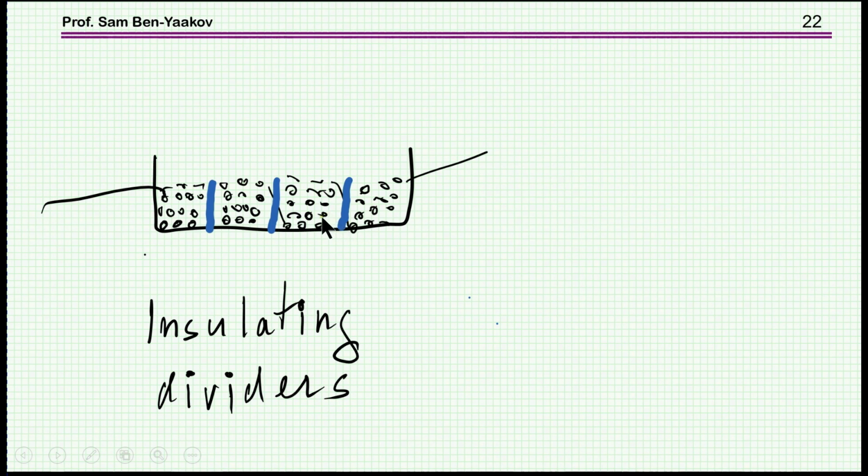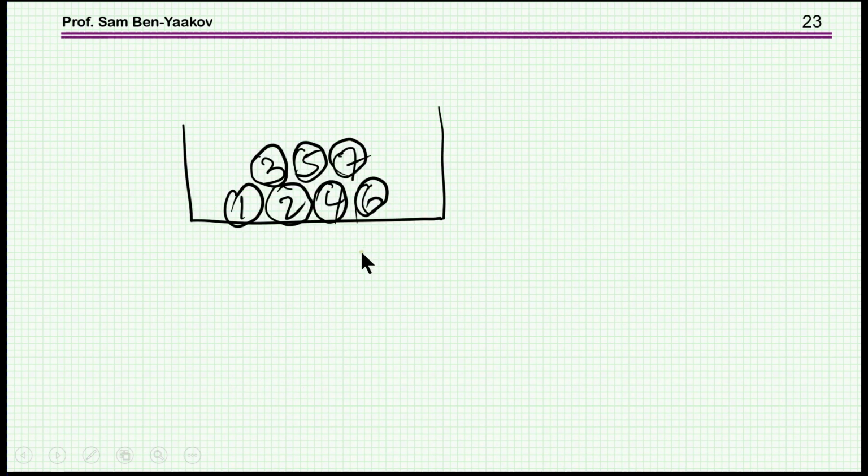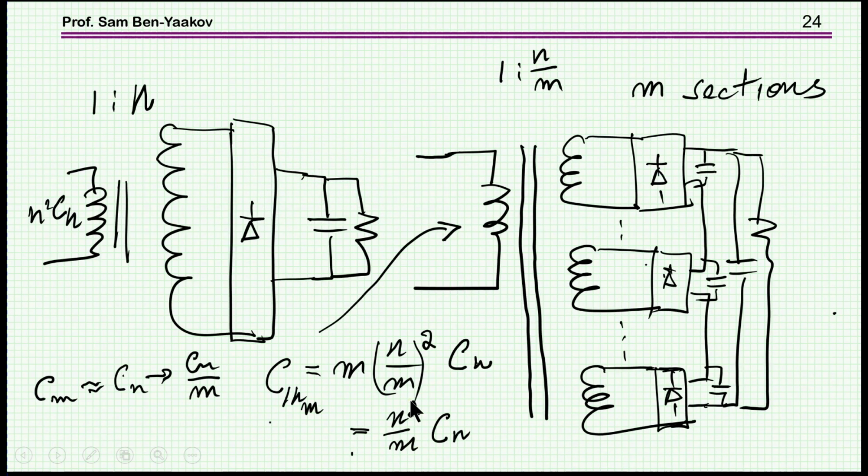so you can have a high voltage transformer on secondary here. Another way would be to wind it in a sort of a jigsaw way. Start with one turn, second turn, third turn, fourth turn, fifth turn, etc. By this, you minimize the voltage difference between the turns. You don't go all the way and then come back, but you have a smaller, of course, voltage drop in between these layers.